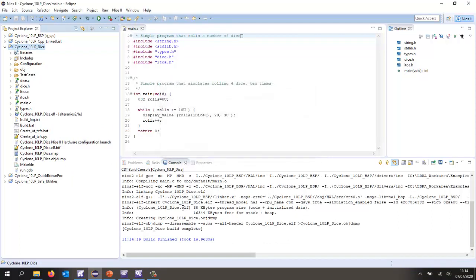So the first thing I'd like to be able to do is look at my code and see, well, is it compliant to a coding standard such as MISRA 2012? I'd also like to be able to look at some of the functions inside my code and find out how complex they are. What's the cyclomatic complexity of some of the functions? I'd then like to be able to execute the code, and as the code executes, find out how much of this code we have actually exercised. And then finally, I'd like to be able to take a particular function and do some unit testing in order to get 100% statement, branch, and MCDC coverage on it.